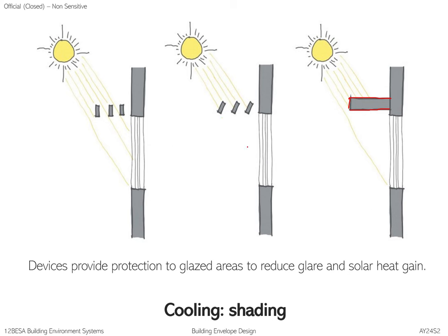So let's say you just compare. In the first scenario, you're using a louver system, a horizontal louver system. In this spacing and orientation, if you project the lines from the sun, you realize that there is a little bit of direct sunlight that will enter the space and hit the glazed areas, whereas the rest is diffused away. Even the diffuse light has a certain quality that can light up the interior space, but probably not as deep into the space as direct sunlight.